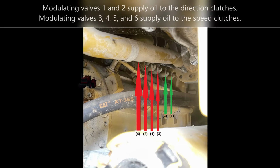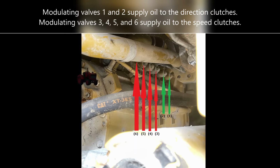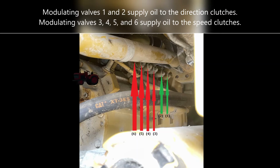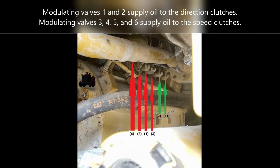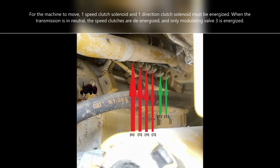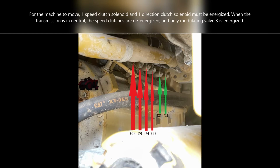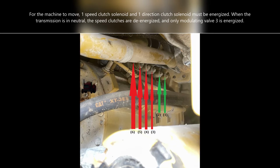The hydraulic pressure to the clutch is applied electrically through 6 transmission modulating valves. The modulating valves are used by the powertrain ECM to modulate the oil pressure that is sent to the individual clutches. The more current is sent through the powertrain ECM to the modulating valves, the more oil pressure there is in the clutch. So that also means the less current is sent to the modulating valves, the less pressure is being sent to the clutches.